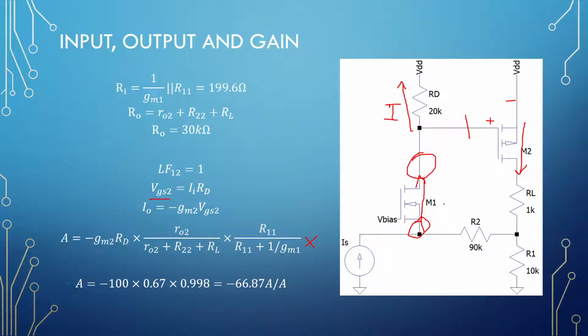You can do this problem with a voltage amplifier configuration. So this will be gm1 multiplied by this transistor right here, and then you have to do the conversion of a second transistor, and it will get hairy quite quickly. And then you also need to include some of our loading effects as well. Okay, this is by far the simplest way, is just seeing that, oh, the current flowing here and the voltage here should be the same, and the current is being buffered.